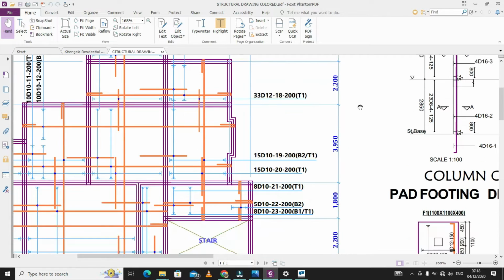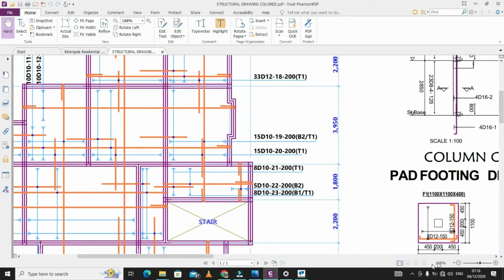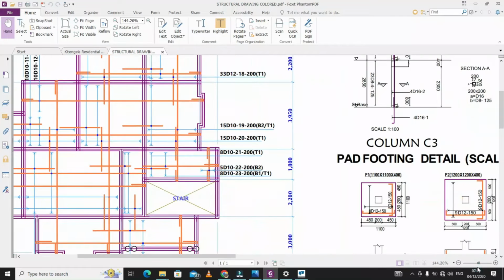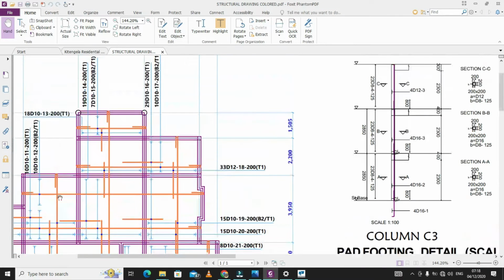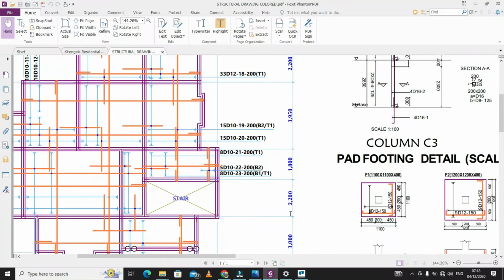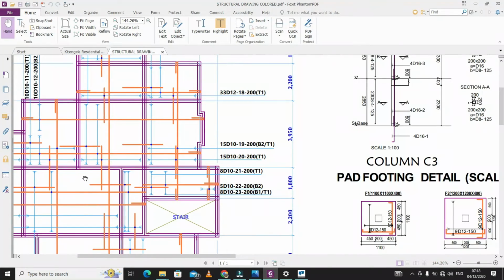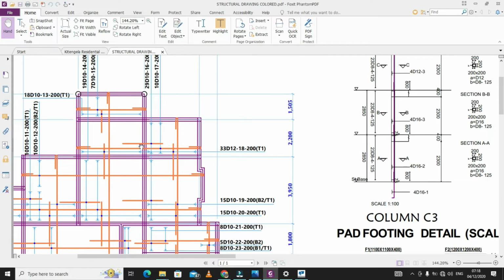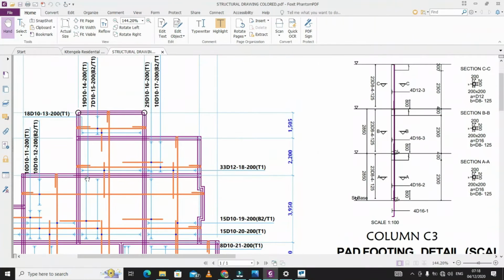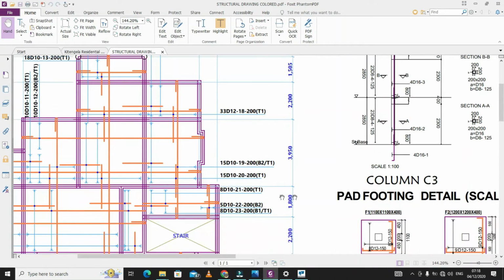Normally in design, if you're sure of the critical panel, you can depend on it and calculate all the loads, and it will give you the reinforcement which you can use to reinforce the entire slab. It's a common practice to use the same sizes of bar, mainly for the main reinforcement, with the same spacing.